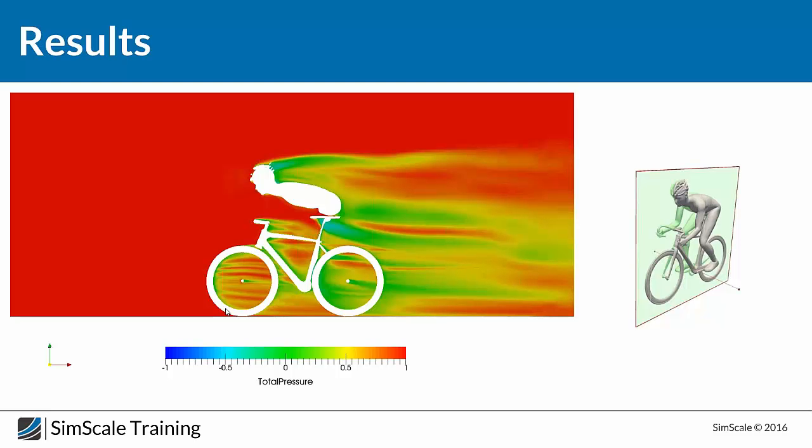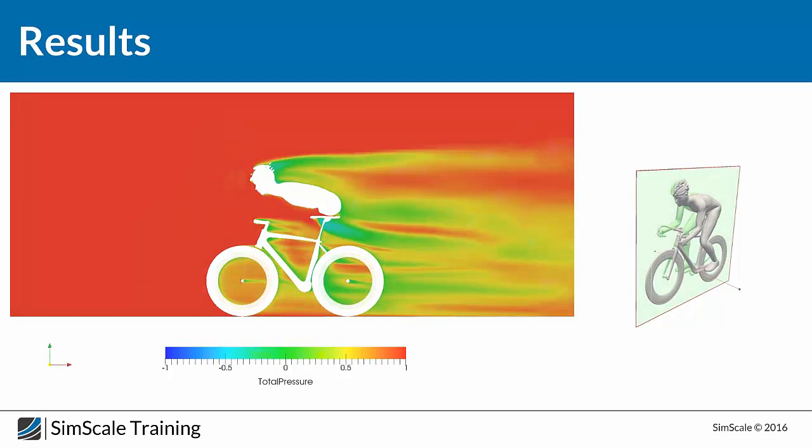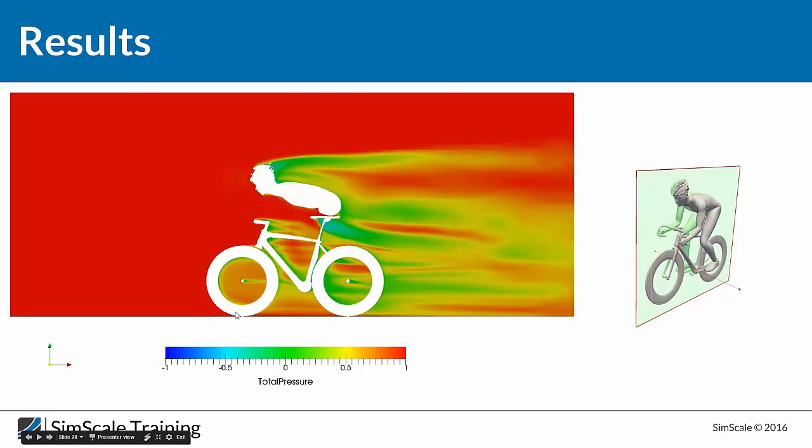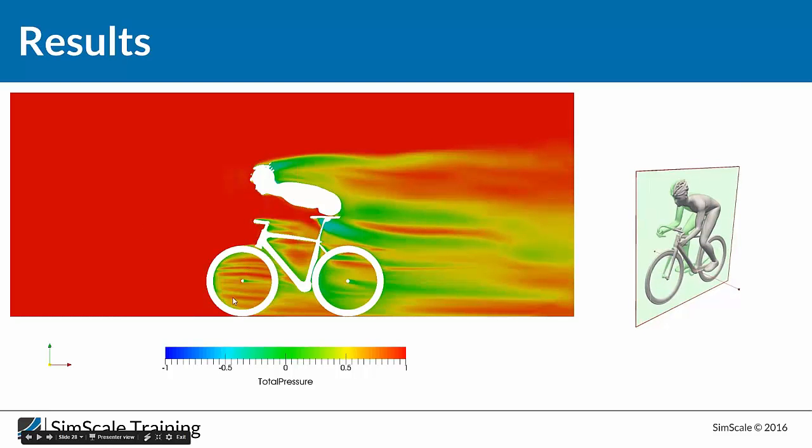But now it's the surprising result: when we use the large tires. The large tires create a really smooth flow behind them, and that's really important to reduce the drag of the tires. I can show you again, if you can focus here on the tire. For the mid design, we can see that the flow is really turbulent. There is significant separation over here.